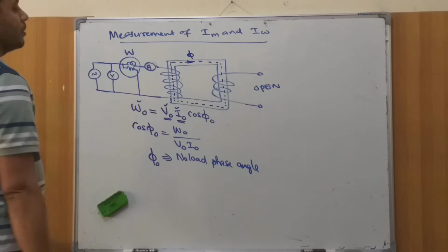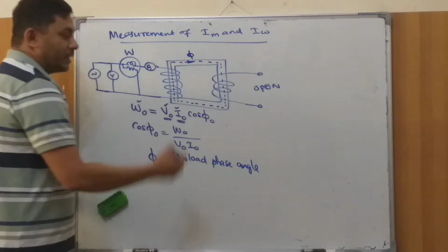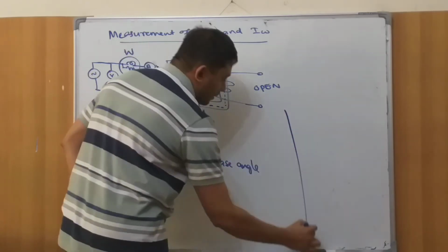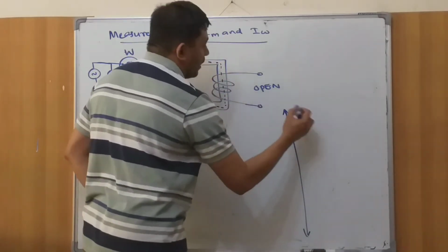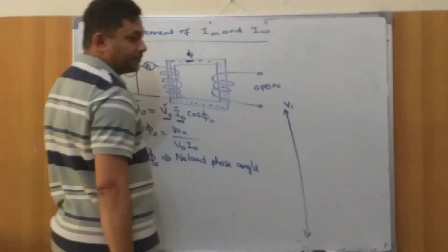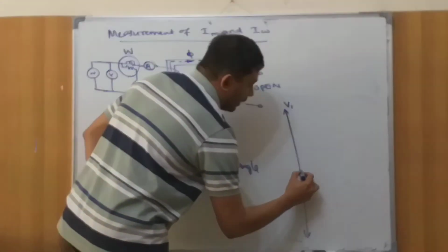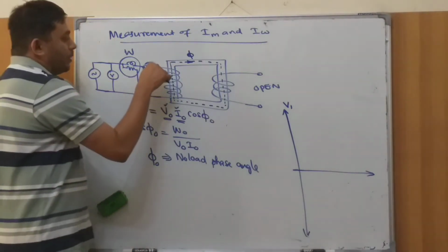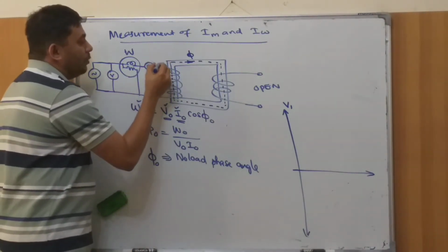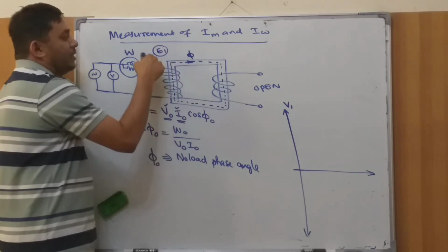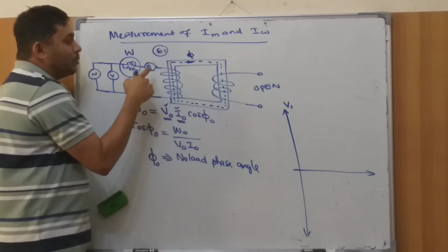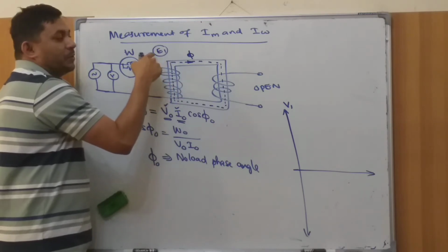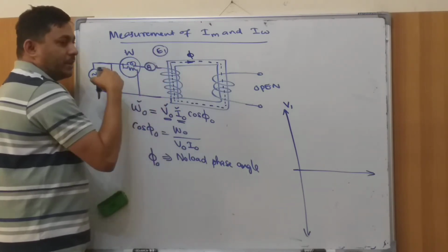Now based on that we are going to draw a phasor diagram, or a vector diagram. So I'm just drawing now a phasor diagram. This is a vertical axis here, and assume that we are applying V1. Okay, so there is a middle line here. So this I am marking is V1. Now, let us look at this way. You know what E1 is, right? E1 is the induced EMF in the primary. And what is the reason for this induced EMF, or who helped induce the E1? It is nothing but V1, right?